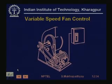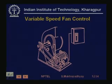What is the third method? The third method, which is a very energy saving method, is variable speed fan control. You do not put any damper, but rather you change the speed of the fan and reduce it when you require less flow. But for that you require a variable speed drive of the motor, and much more sophisticated technology is required, especially when the motor is large, compared to dampers or valves. But as we shall see, they can save a considerable amount of energy.